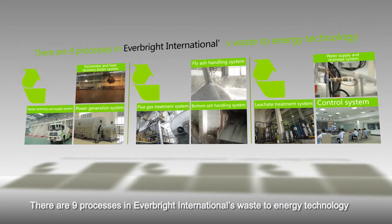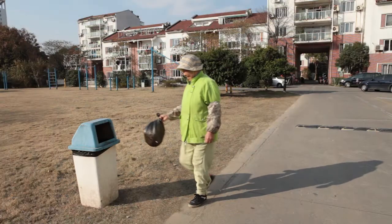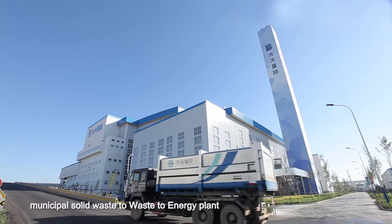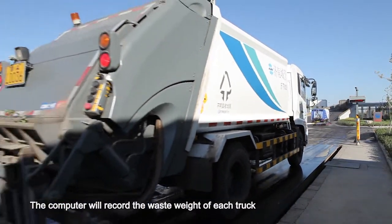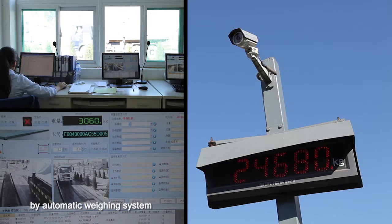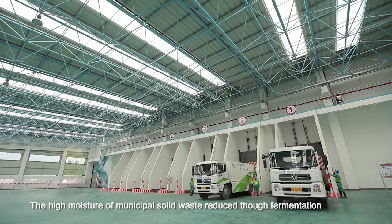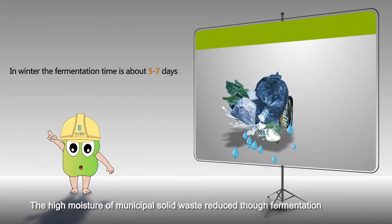There are 9 processes in Everbright International's waste-to-energy technology. 1. Waste reception. Liaising with the local government, waste trucks transport the unrecyclable municipal solid waste to waste-to-energy plants. The computer will record the waste weight of each truck by automatic weighing system, and then the trucks unload the waste into the waste bunker. The high moisture of the municipal solid waste is reduced through fermentation.